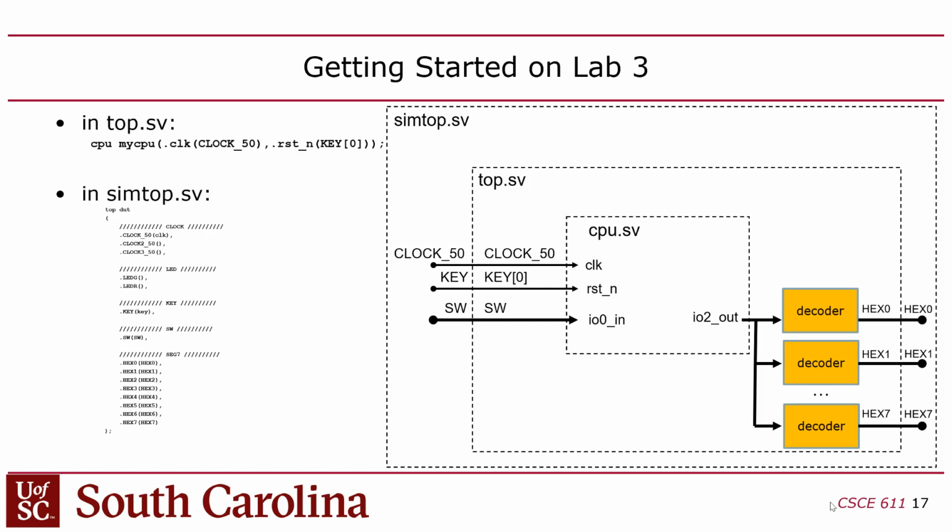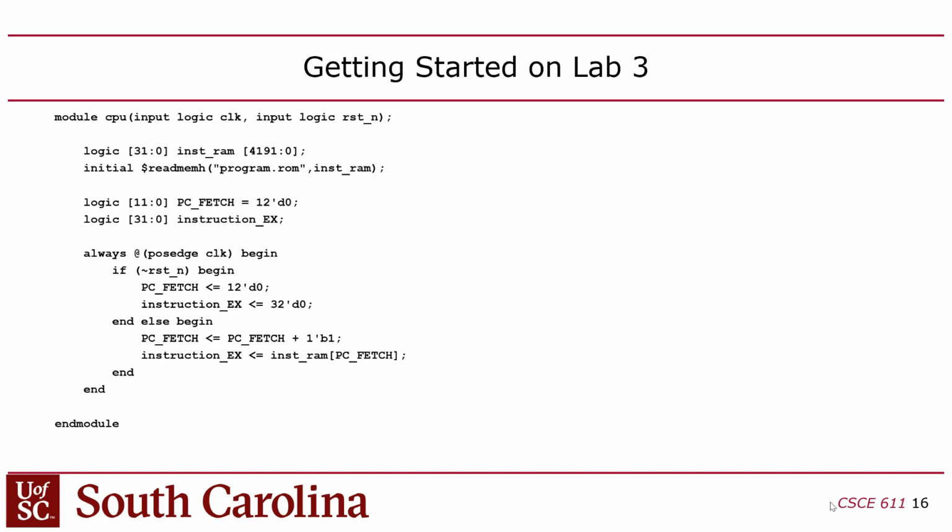And then you're also going to have ALU.SV, that's the ALU that I mentioned we're giving you, and the regfile 32 by 32.SV, we're giving you that. So I think there's 4, right? So when you start this project, the first thing you should do is create a 5th file, which is CPU.SV. Okay, so start with that. Just start with CPU.